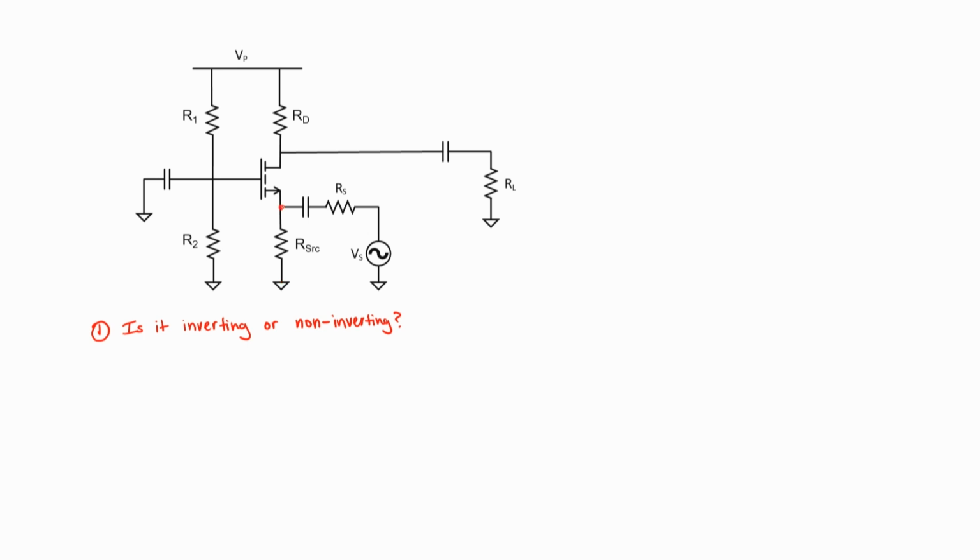Let's call this voltage here VSRC, and I'm using VSRC to distinguish it from the signal voltage over here. Our signal voltage is going to be an AC voltage that rises and falls. It might be attenuated a little bit when it goes across this capacitor, but in any case, it's going to add to or subtract from the DC source voltage.